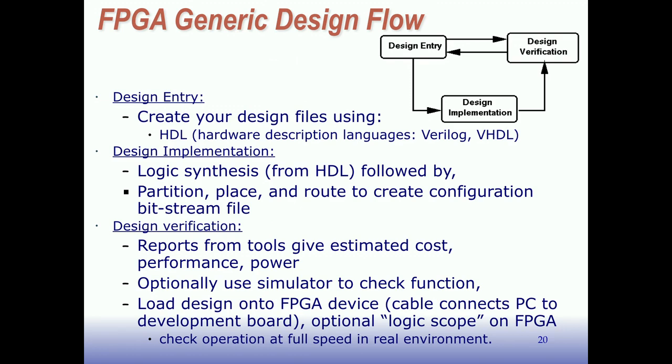And then eventually you can load the design onto the FPGA and check it out in the real world. Blink some lights, connect to video. There are some tools that let you build a logic scope on the FPGA. Along with your design, the tools will embed what looks like a logic analyzer so you can watch some of the signals change inside the FPGA, which is a nice way to debug it. You get visibility to some of the internal signals to help debug your design.